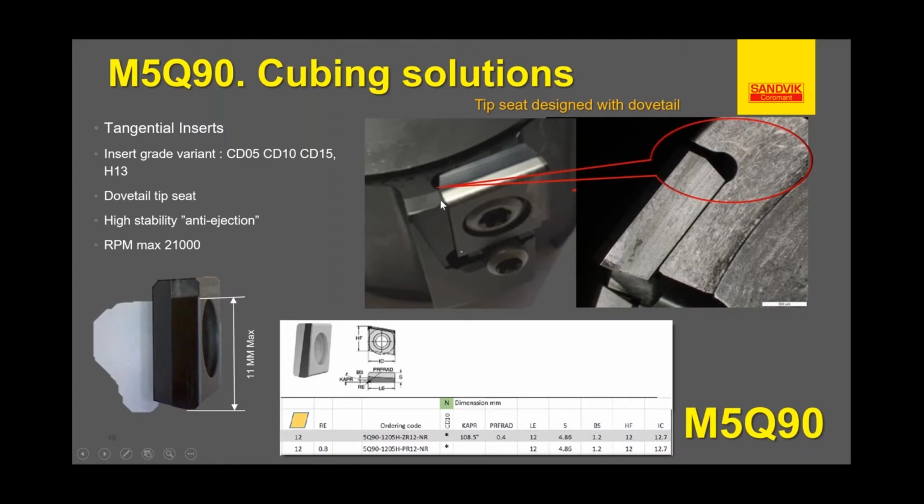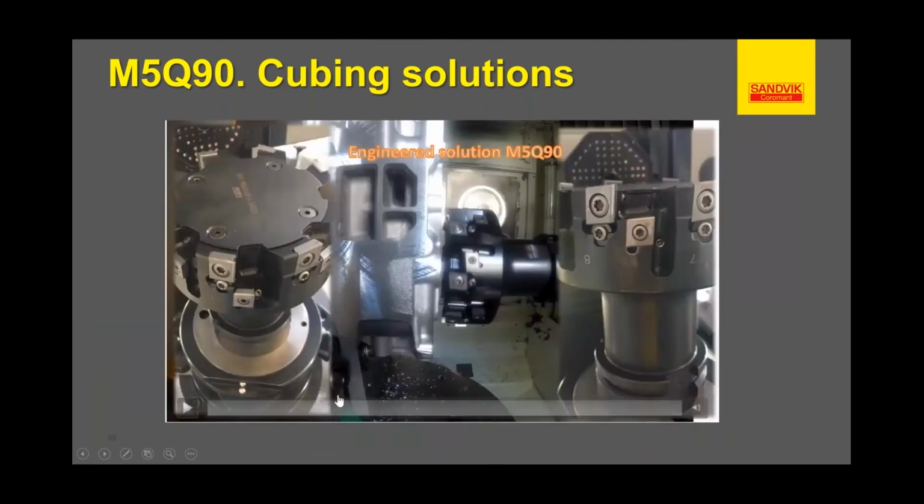So there's a little dovetail feature in here that secures the insert in the pocket so it doesn't put all the load on the screw, because if you throw an insert out at high speed, it's very, very dangerous. So that's why we developed this locking mechanism.